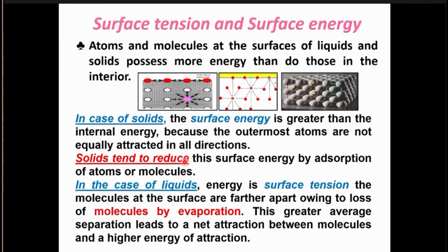So high surface energy will pull the adherent towards itself, reducing the contact angle and giving us better adhesion. Similarly, in the case of adhesives, we need low surface tension so they can give us a low contact angle and better adhesion.